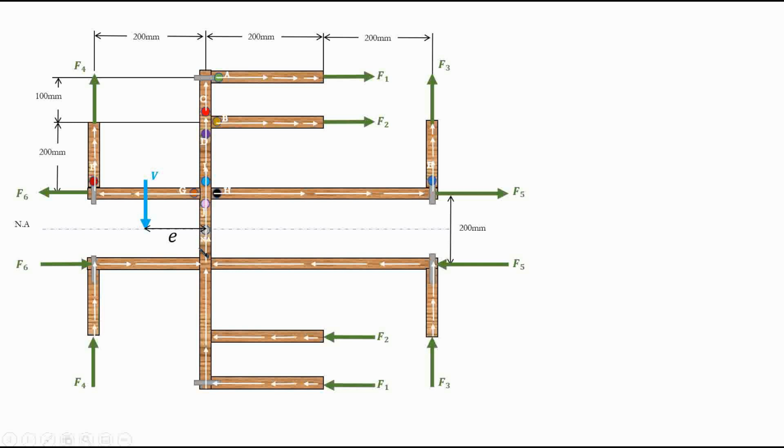Another point that I can make is that your shear center will be always, or usually at least, to the side of less material, in my experience. So if this is your web, and you're going to decide if it's to the right or the left, it is usually 99% of the time to the left, because you have less material here and consequently lower forces. This is just by experience, just a rule of thumb.